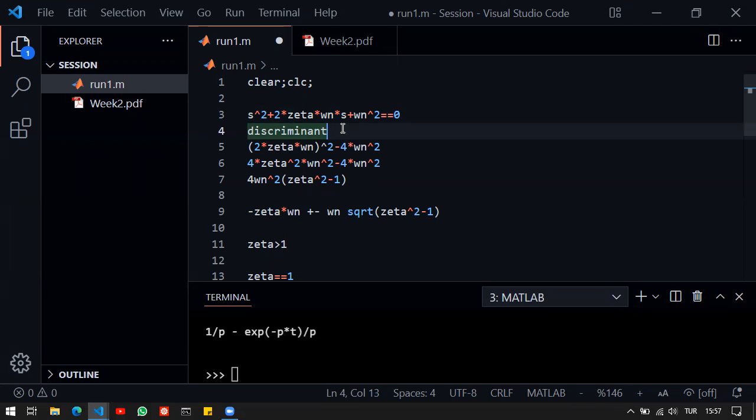Even though we have a third order system, we want to have two poles according to the formulas, according to zeta and omega n, and then the third pole should be placed far away, if it's possible. Because in the upcoming weeks, we will see that this is a good strategy. If you have only the second order part to be dominant and the other non-dominant parts are pushed away, that is a good control strategy.